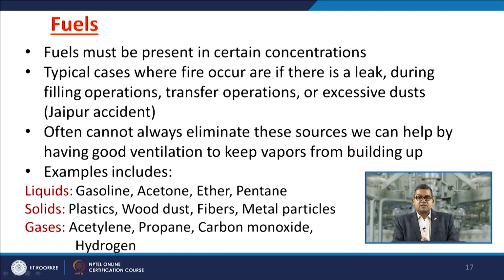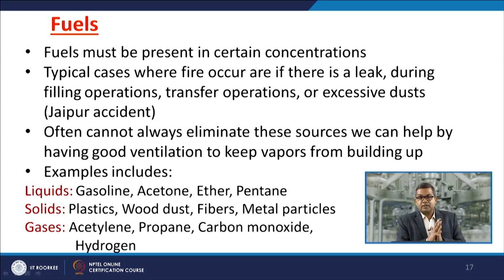Now, how can we assess the necessary conditions for the formation of the fire triangle? Prima facie, the first thing that comes to our mind is the fuel, because when we go to a petrol pump or to the kitchen, our subconscious mind says there is the presence of LPG. We don't bother about the source of ignition or the availability of oxygen at the source. So, fuel. Let us have a brief discussion about fuel. Fuel must be present in a certain concentration. Remember, there is a stoichiometric demand of fuel. Let us have a basic equation of methane burning.